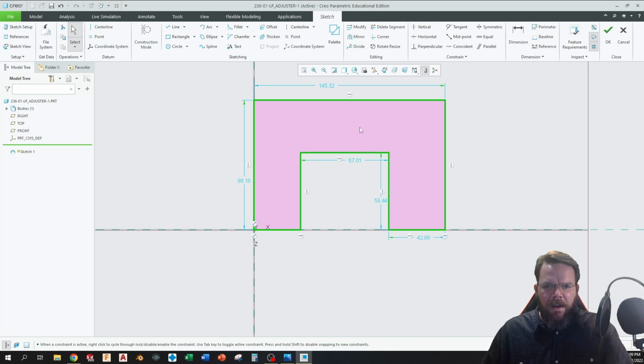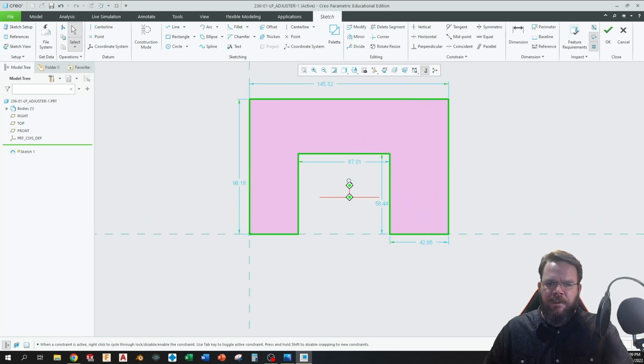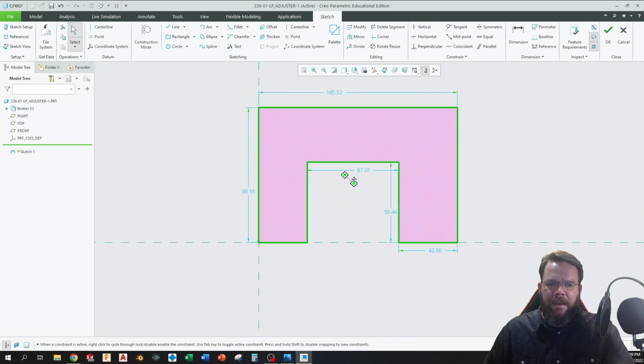So zoom in here, and then I also want to pan. Now to pan, oh, wrong one. There's different key combinations that you can use. Control, that's one I just used. Control and your middle mouse wheel clicked, that's another zoom. Shift with your middle mouse wheel, that's pan.